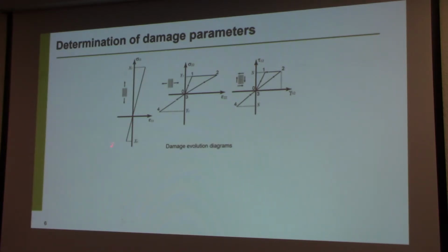As I said, we assume brittle failure, and for other strain components, we assume a constant stress value after we achieve failure stress in this direction. Of course, we can drop this curve to some stress level if it is known, or if we have some extended data with exact behavior for the load and corresponding stress, it also can be applied.